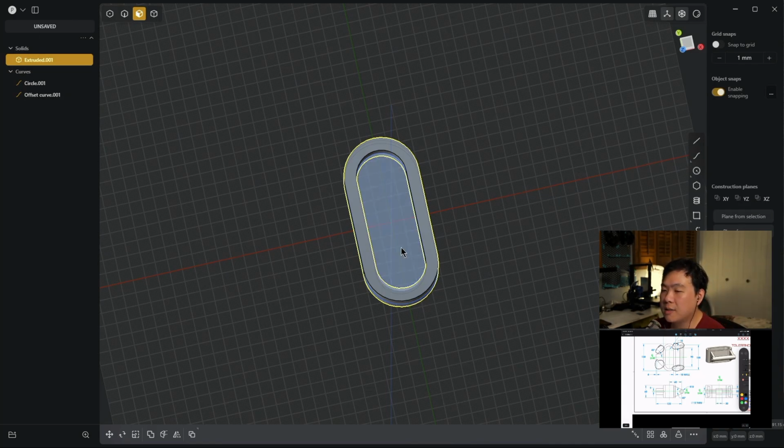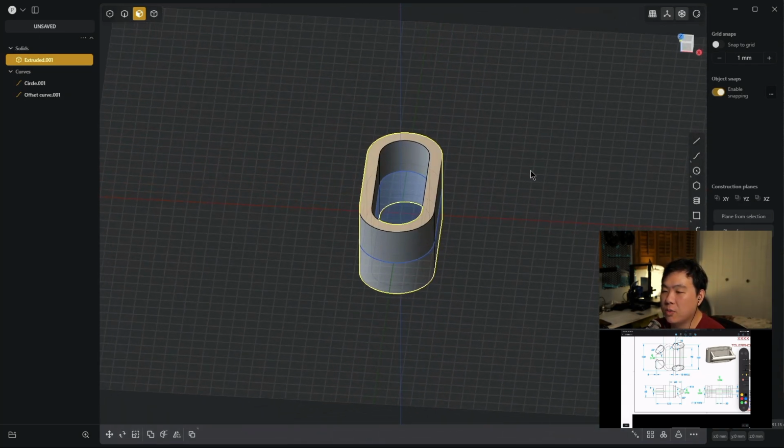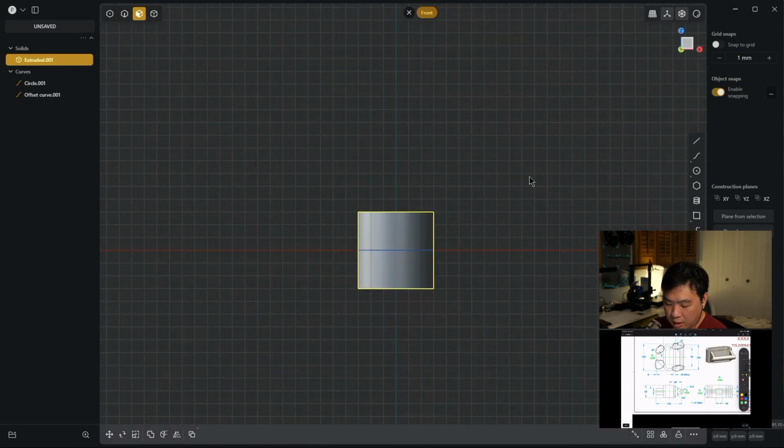So looking at this model, I can now switch to the front view, and here I'm going to select the corner rectangle tool, but I'm going to click on the x-axis, and once I start dragging, notice that on the bottom right there's the shortcut, and it tells you to switch from corner rectangle to center. I can press the C shortcut, which is what I'm going to do. And now it's centered along the x-axis.